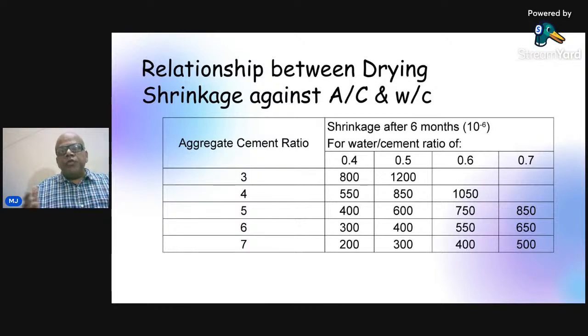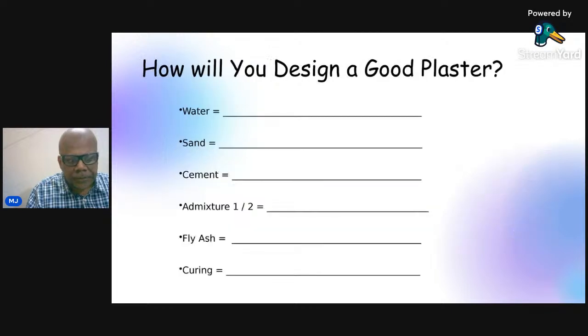And therefore in huge structures, look at the roads, you have to leave grooves either for shrinkage to take place or for shrinkage cracks to appear at a specific place. So cracking of concrete, can we avoid it? We cannot avoid it. You look at any large building where there is external plaster done. Let's go to plaster. Very nice point about plaster as we go ahead.